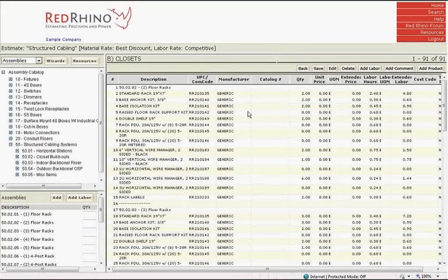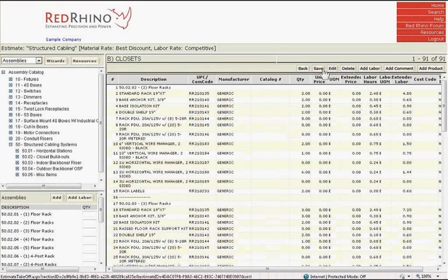Next, I want to demonstrate some editing functions. Once all the material input is completed in the section, I recommend you go through and delete each line of material that has a 0 quantity. Later, you'll want to create a material list, and the materials with 0 quantities would show up on those material lists unless you delete them. You can delete one line at a time just by clicking on the line and clicking the delete button, then click Save. Always make sure you save your deletion.